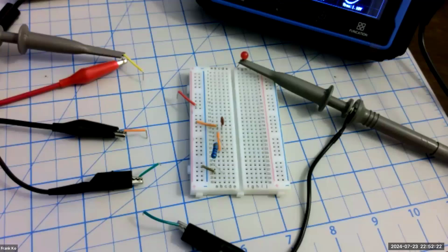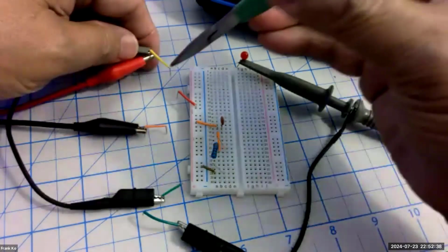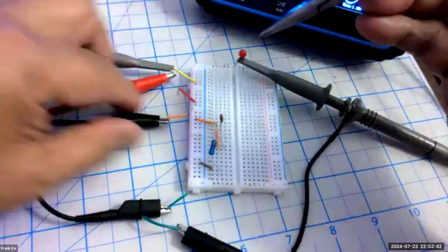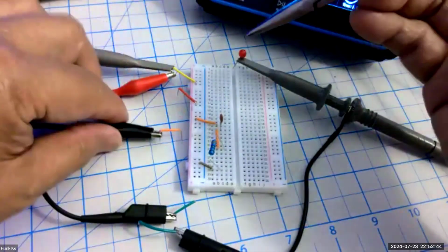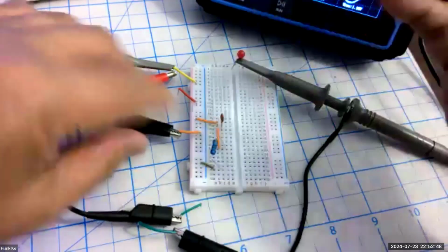Okay, I've just switched boards. No longer have that voltage divider. I've got what's known as the RC time constant, RC circuit. And this is what we're going to use to demonstrate some phase relationships, okay? So I've got my input and my channel 1 connection. I'm going to hook up to the red rail there. I'm going to hook up my black ground alligator to a blue rail, some place that's convenient.